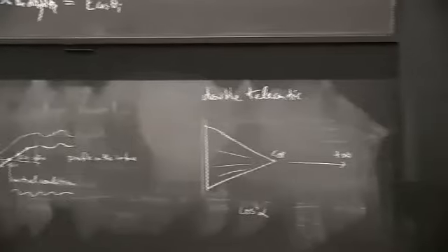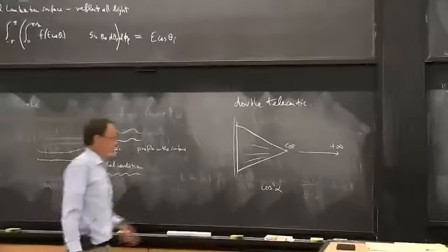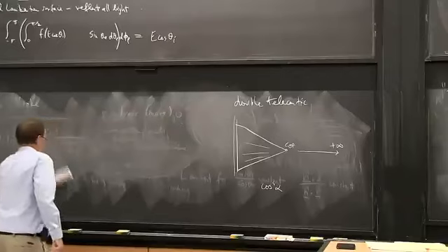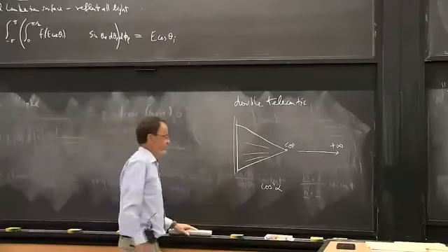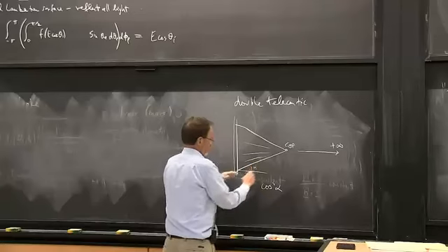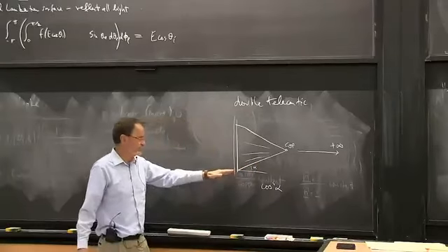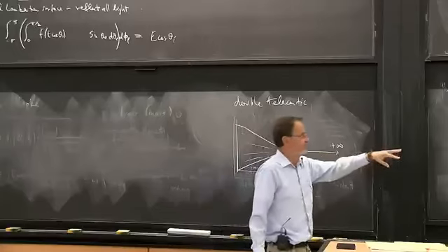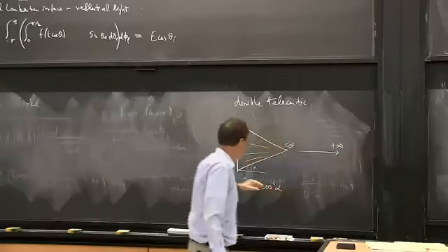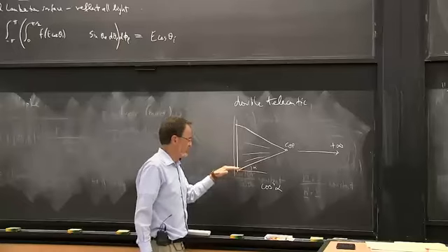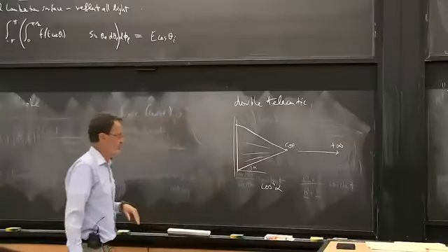So why does this cosine to the fourth go away? Well, because that came from the inclination of the rays coming into the sensors. And so by moving the nodal point way out, now the radiation reaching a particular sensor is coming in perpendicular to the sensor.